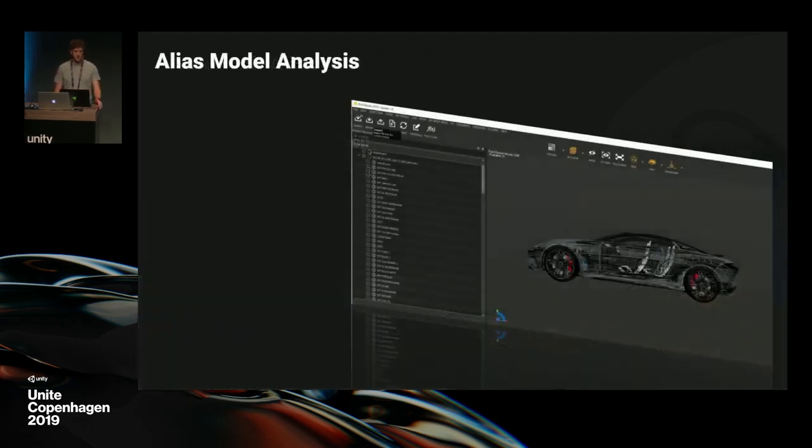But first, good CAD data preparation starts with good analysis of your model. You need to know what's inside. So first, let's take a look at how the scene tree is defined, and let's look for important information. First, hierarchy levels. Here we have 1 part per alias layer, all at the same level, which is not very practical for real-time animation. Then regarding the number of parts, here we have 158 unique parts, which is really not that big, but still needs to be merged smartly for real-time use, of course.